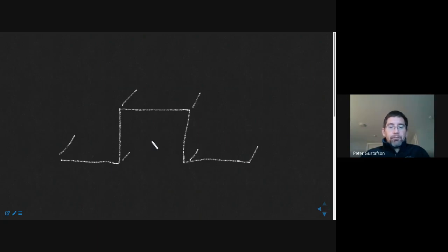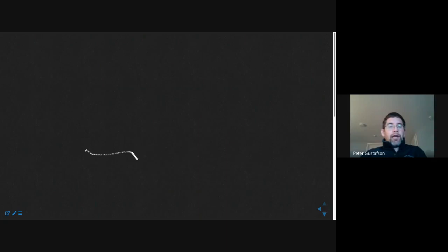Okay, this is our beam, right? So simplify it into a 2D cross section, looked like this. Now, if I applied the load here, you might say intuitively that that thing is not going to twist. And what I mean by twist is it's not going to end up looking like this, right? It's going to bend.